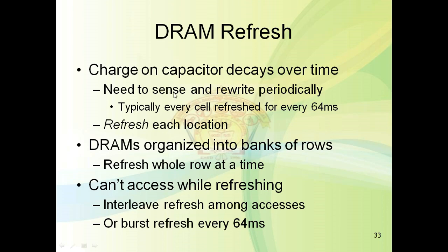refreshment of the data. Typically every cell is refreshed every 64 milliseconds, which is given by the manufacturer. Every cell is refreshed after every 64 milliseconds, so we have to refresh each memory cell, or each memory location.